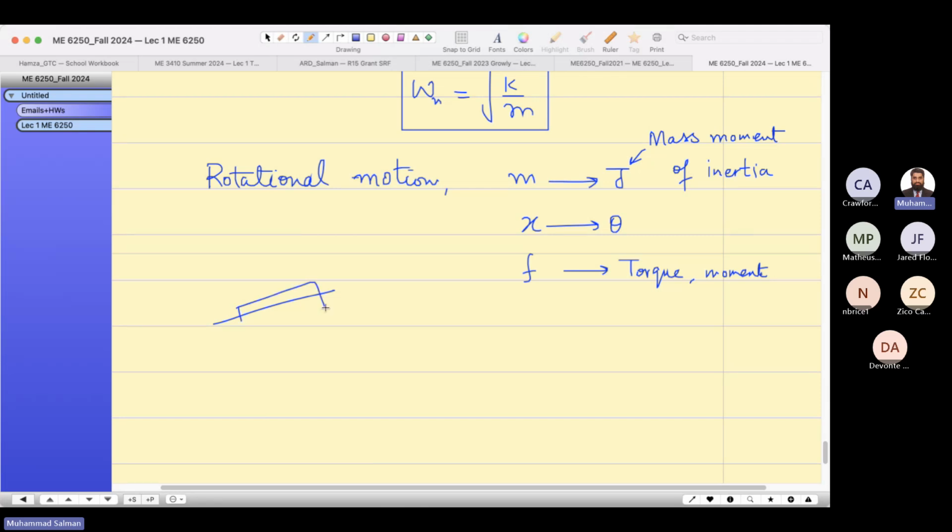So this is like a shaft here, and now guys, this is rotating. Let me redraw this one a little bit. So I want to show you, usually this is the way we show the rotational motion when we apply the torque. So can I write down like this? So the resisting torque is minus k theta. The minus sign shows that it is against the applied torque. Always the shaft will try to resist the applied torque when it is held on one end.